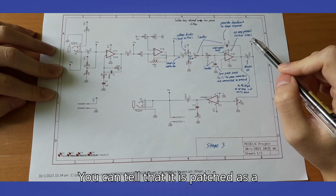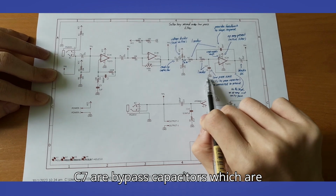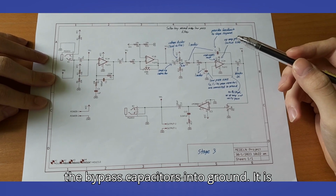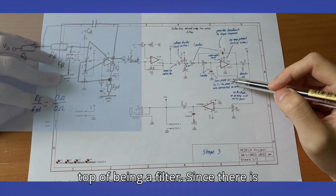You can tell that it is patched as a low-pass filter since capacitors C6 and C7 are bypass capacitors, which are connected to ground. What this means is that high frequencies are passed through the bypass capacitors into ground. It is also an active filter since it has an op-amp, which will provide voltage gain on top of being a filter.